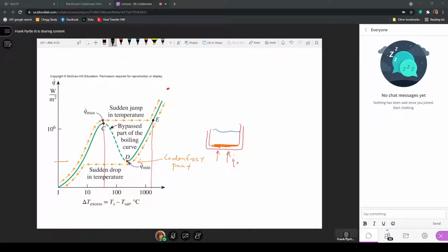The transition boiling is along this dashed green line, and this is actually not a portion of the pool boiling curve that you can get in what is called a heat flux controlled experiment. These orange arrows indicate the direction for heat transfer as we heat the surface, so that heat transfer occurs into the liquid to get to the boiling regimes.